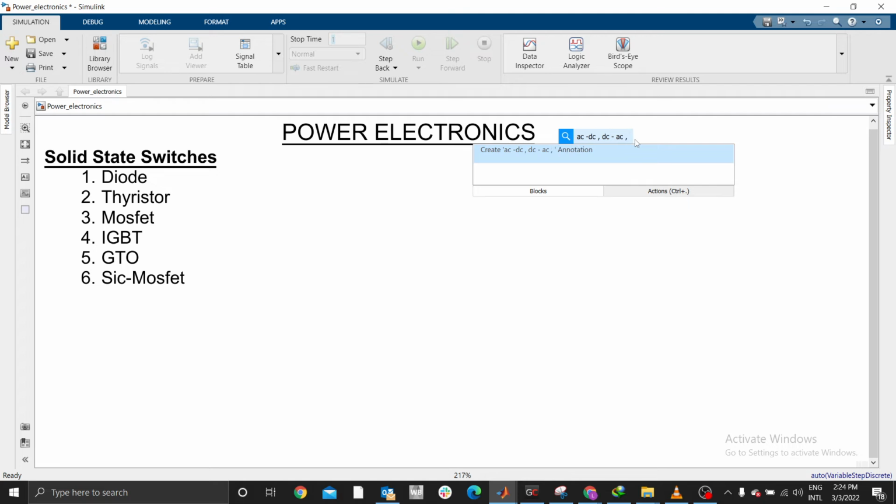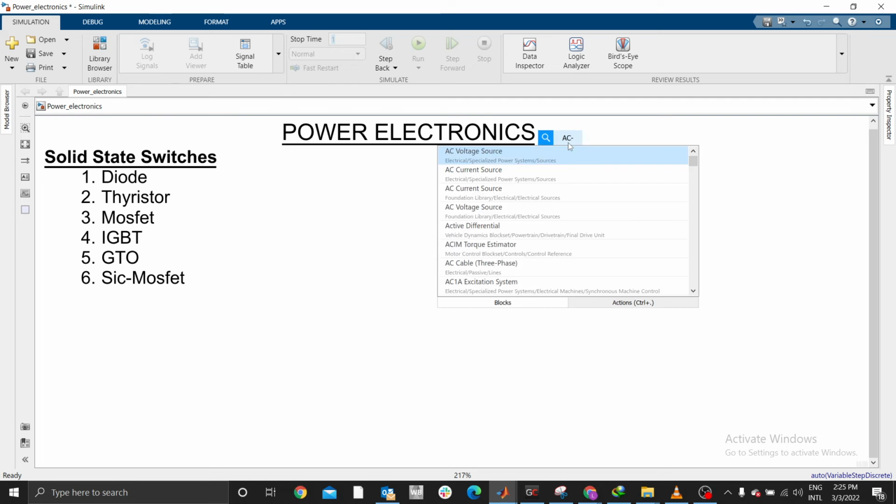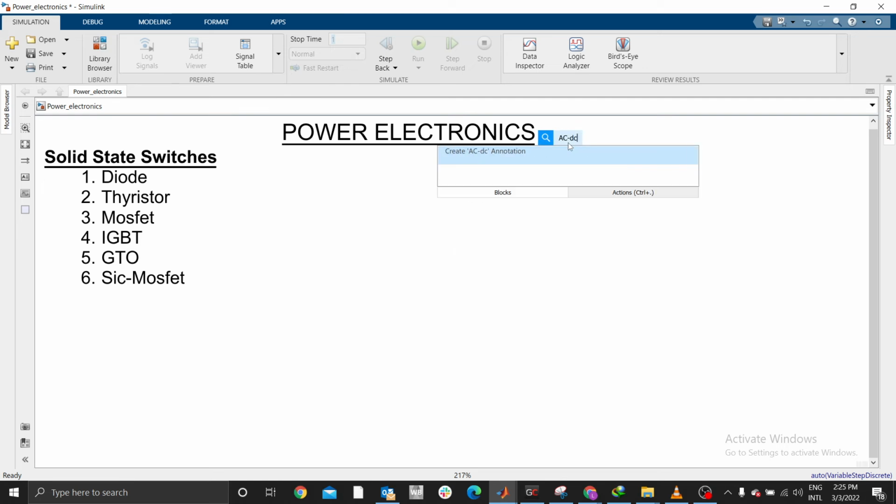Converters also change AC to DC, but most converters use thyristors. Rectifiers use diodes, and most of the inverters use MOSFETs, IGBTs, while the converters use thyristors, most of them. We have said rectifiers change AC to DC, and most of them use diodes. Converters, most of them use thyristors, and still change AC to DC. Also, we have some scenarios whereby the converters change DC to DC.